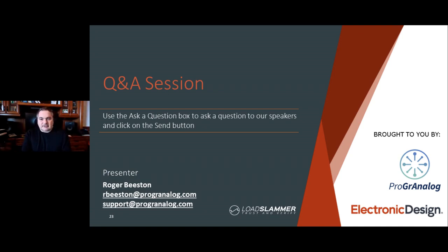There are some guidelines that Xilinx offers on their devices, and there are two guidelines. There's a slew rate, and you could turn that into a rise time as well, if you've figured out what your worst case event peak current is through the PDN. There's also a frequency domain analysis that you can get that information from Xilinx as well.